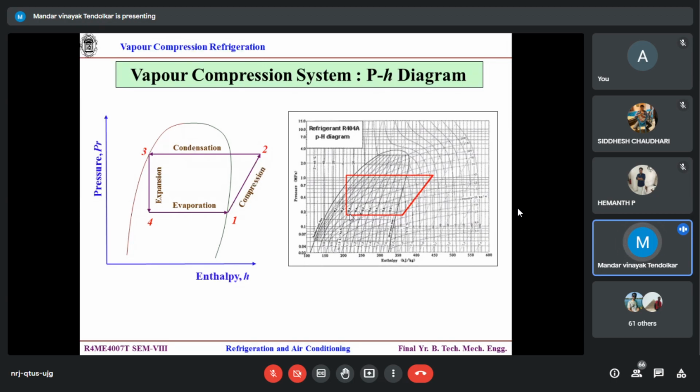So we design the process 3 to 4, or rather the expansion valve, in such a way that I can stick as close as possible to the isenthalpic assumption. In reality, in practice, isenthalpic expansion never takes place. It is very easy to assume for the gaseous part, but not for the liquid part. Do you agree?